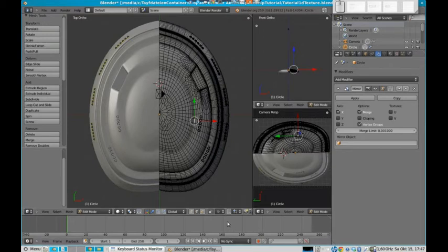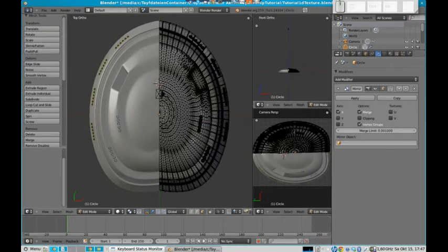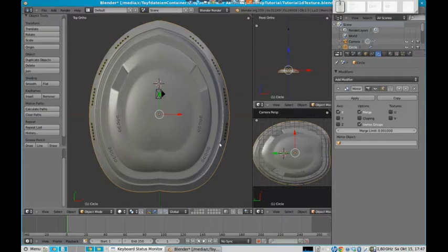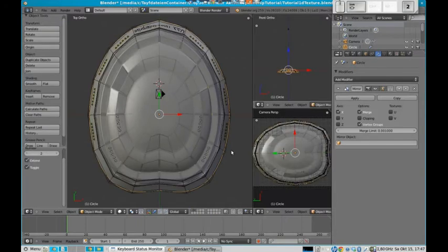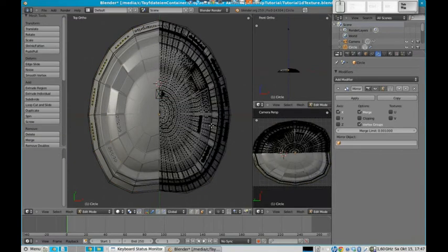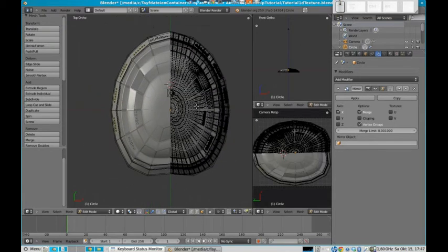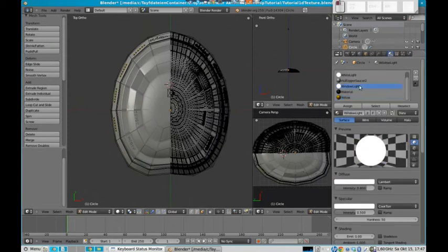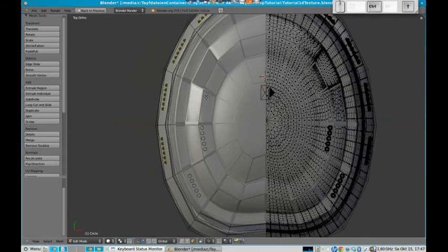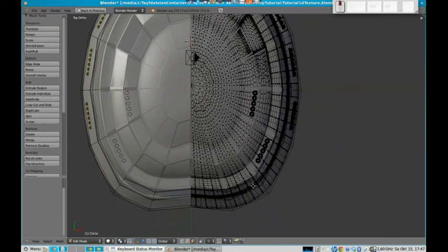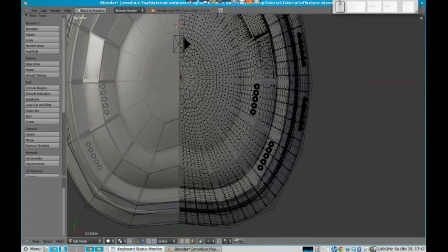So let's select face selection. But now we lost, of course, the grid, so we don't know anymore exactly where our grid is. So let's go back to object mode and activate our grid, and then go back to edit mode. And now, since everything is so tiny, let's switch to window light, and we should use Control and arrow up to maximize this view. And now something where a lot of patience is needed starts again.